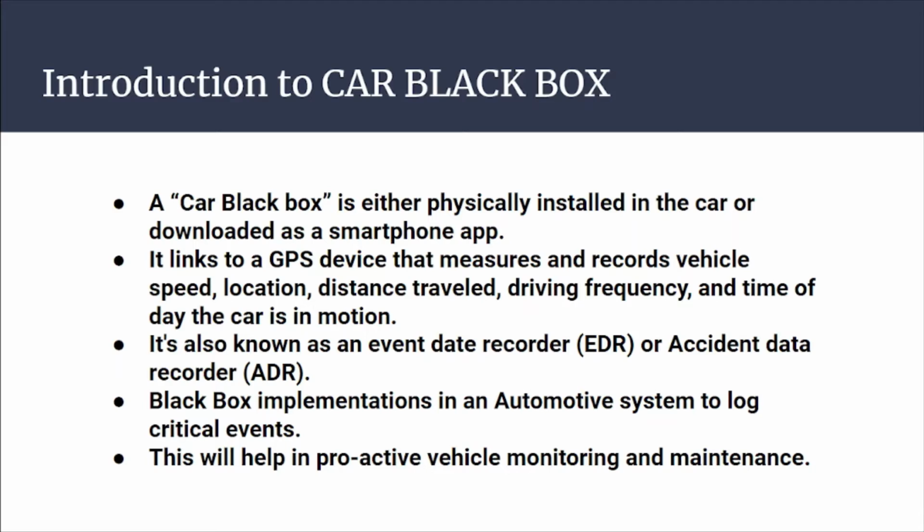The proposed solution is to log all the critical events like the gear shifts with current speed, the engine temperature, fuel consumption per trip, trip distance, etc. The system should allow a password-based access to the transport managers to view or download the log to PC if required.